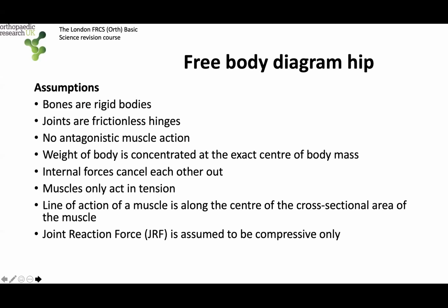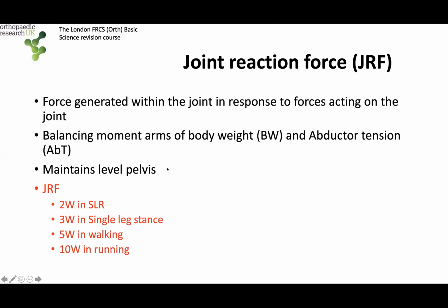Okay, so these are common exam questions, either in the multiple choice questions or indeed in a Viva. When they ask you to draw a free body diagram, you need to be able to rattle these off very quickly. Joint reaction force is the force generated within the joint in response to the forces acting on the joint. Okay, so we're trying to balance the moment arms of the body weight and the abductor tension in order to maintain a level pelvis.